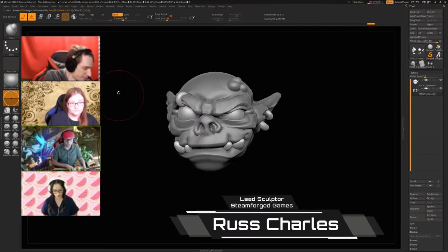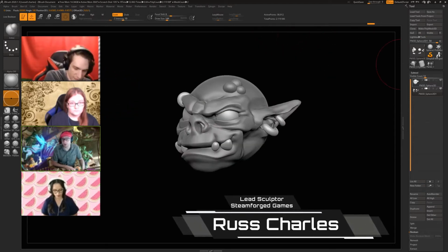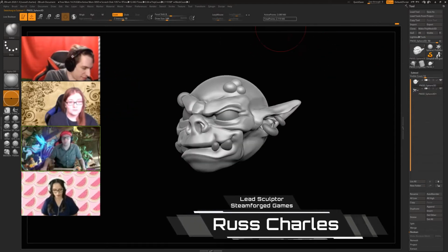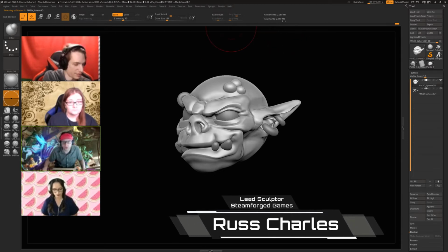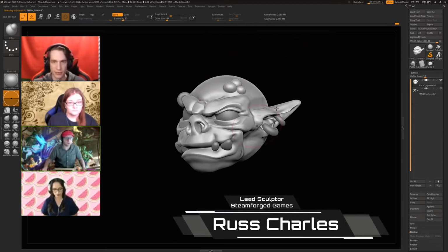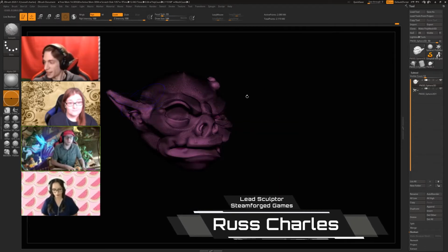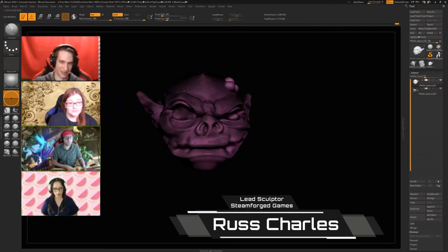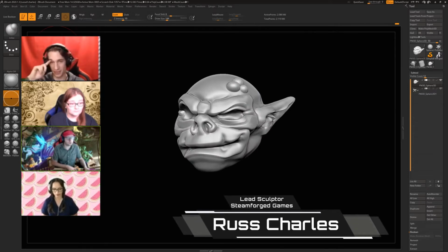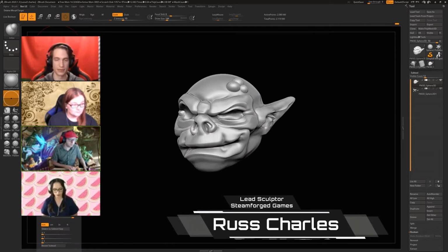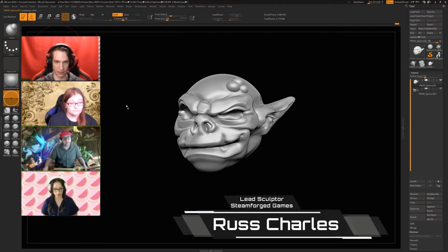Right. So just before we finish, I just wanted to show this. Our model is currently, I don't know how well this will come up because my screen's quite small resolution, but we're at 2.1 million polygons on this head to capture this level of detail. Now, we couldn't ever print that, so what we would do is go to our decimation tools. If we were going to print this, choose maybe 150,000 polys, hit this button, and this will now read our model and process it and turn it into a printable file. So we could then output this and throw this goblin head onto a 3D printer, and I can set the scale of this at any point.